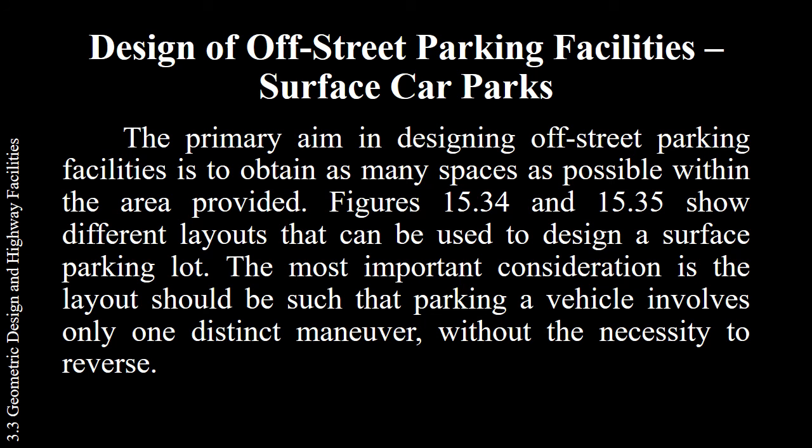Next, design of off-street parking facilities, surface car parks. The primary aim in designing off-street parking facilities is to obtain as many spaces as possible within the area provided. Figures 15.34 and 15.35 show different layouts that can be used to design a surface parking lot.